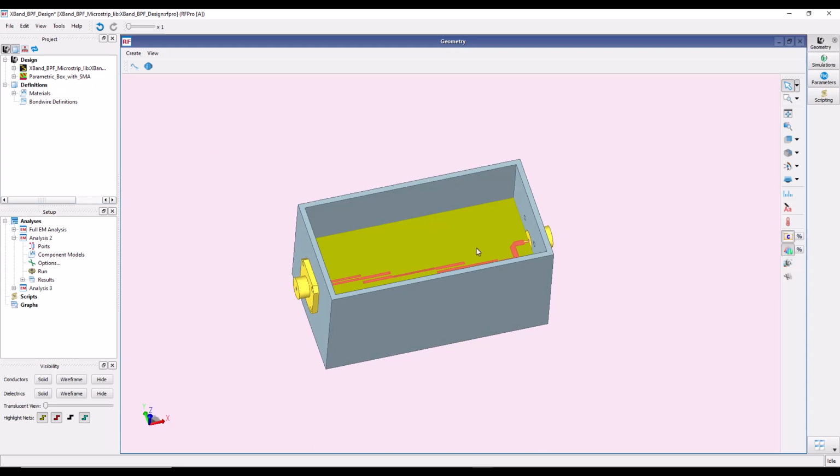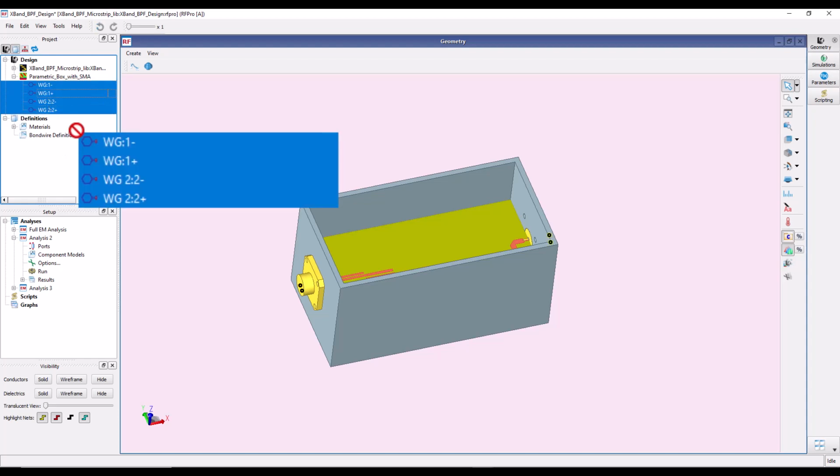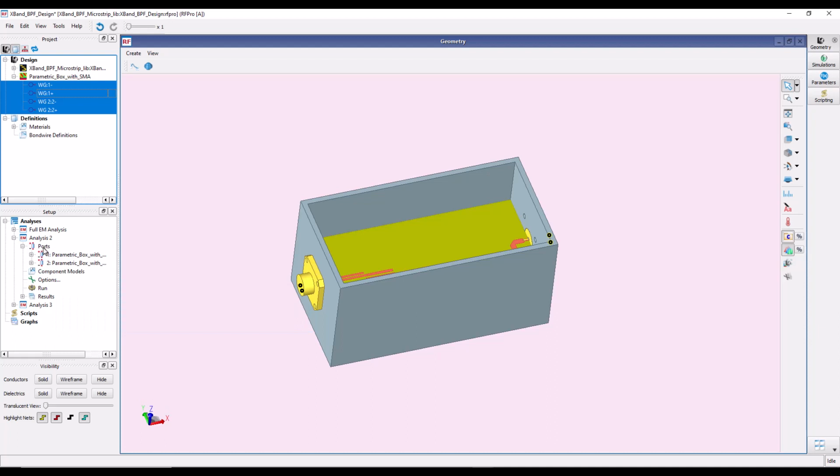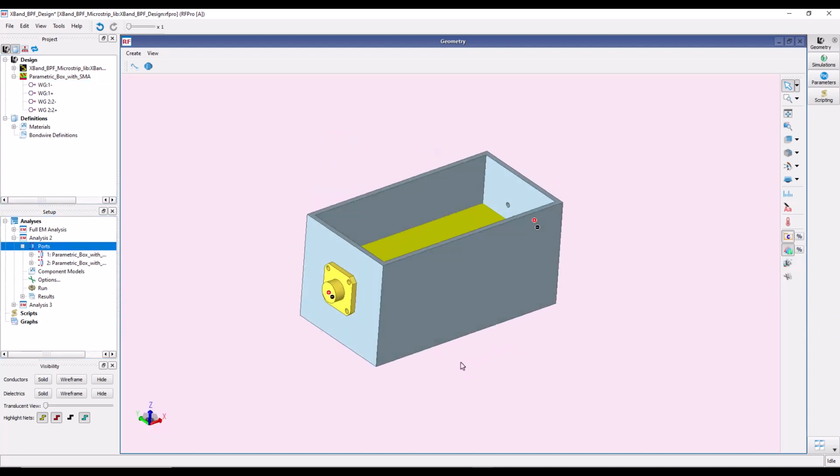Now what we need to do is get the cover and the absorber, and again, if you want to get it right now or you want to set up the FEM simulation first, it's your choice. So right now let me not bring the cover and the absorber. Now let's say I want to set up simulation in this case. Remember, once you expand this 3D box, we already applied a couple of ports in this 3D object, and now what we need to simply do is select those pins and drag and drop them, and here we can create a port, and now you can see you have the ports created on the SMA face.